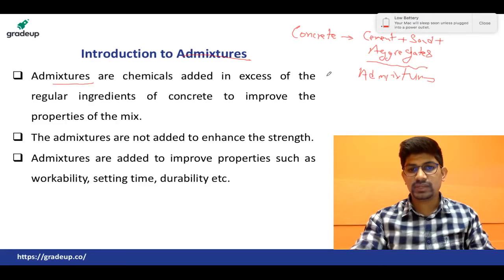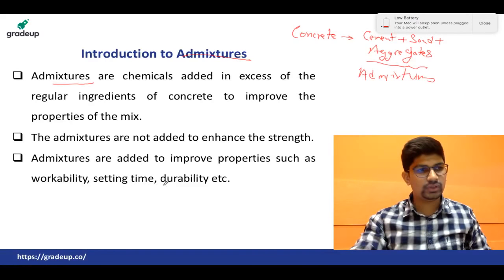Strength wise, admixtures may or may not provide additional strength. It may happen that one or two admixtures definitely help, but admixtures in general are not for improving strength. They are more for the properties such as workability and all. Admixtures are added to improve properties such as workability, setting time, durability.